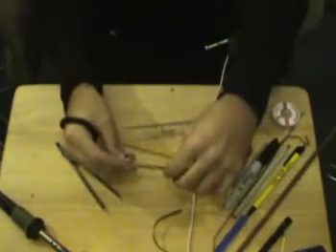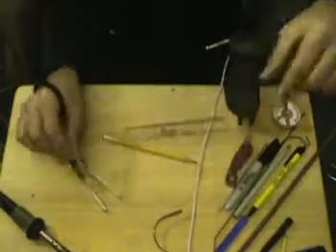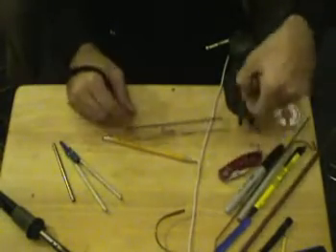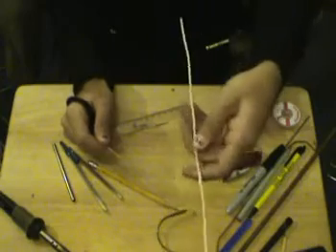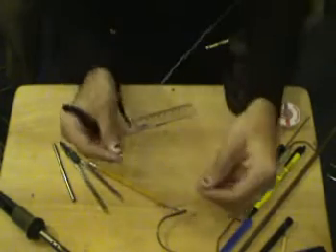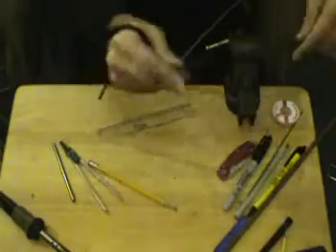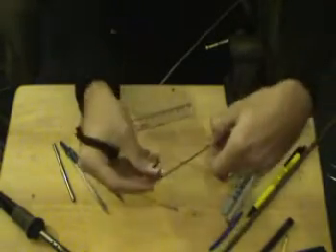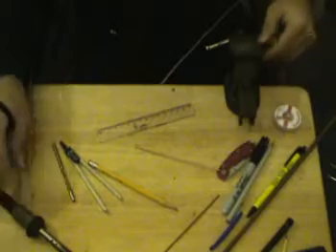So we've got the antenna, and I've marked 2.5 centimeters. As for the actual wire itself, any wire, here's some household power cable that I pulled out of the garbage. I pulled the sheathing off of it just so I can solder it. You can use an old coat hanger. Here's a small length of coat hanger. Just something metal, something conductive, and something you can solder to.